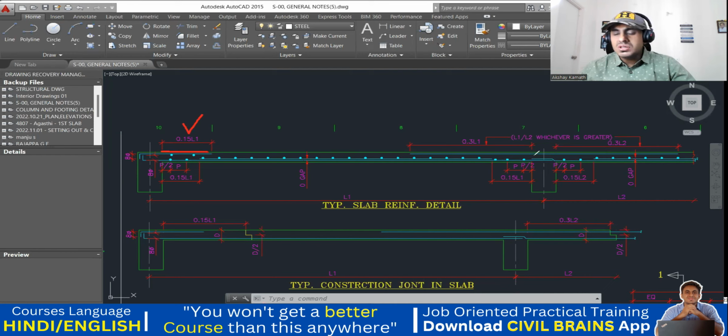And in the middle portion, you have a slab on this side and a slab on this side, so it becomes a continuous span. So again, when you provide a top extra on the left side, you go 0.3 into L1. And here also it will be a top right extra 0.3 into L2. And again, same thing: L1 or L2, whichever is greater, like we did for the beam. Same for the slab. There's nothing much change in the slab.